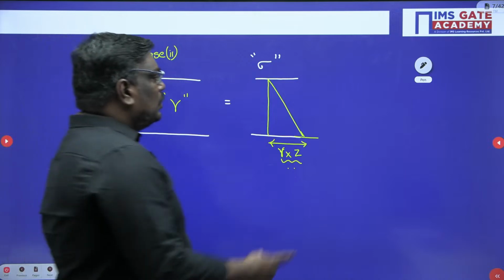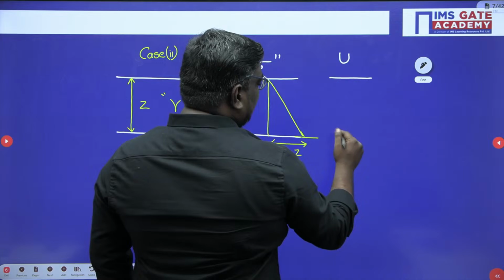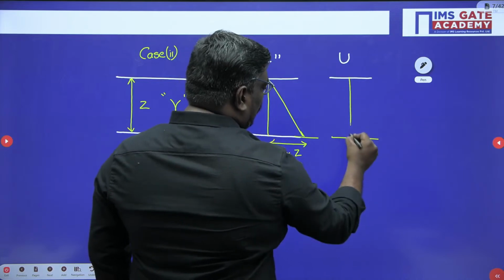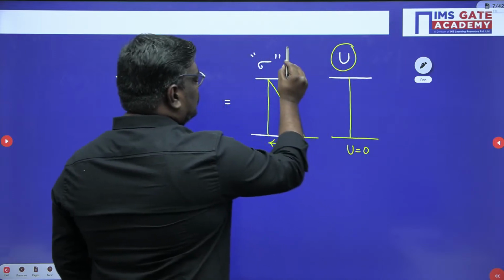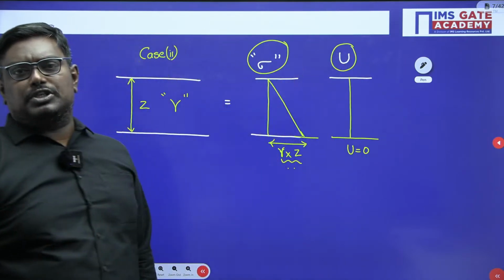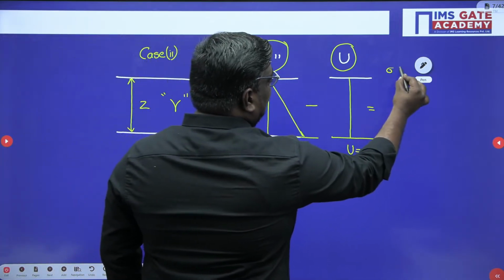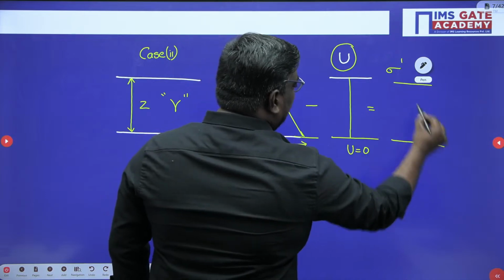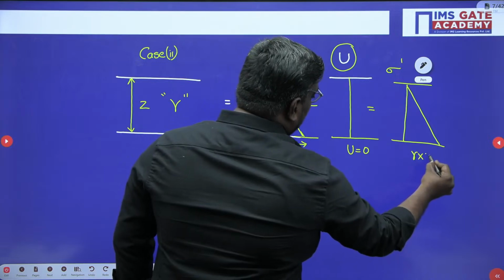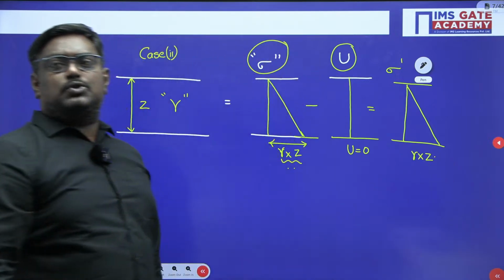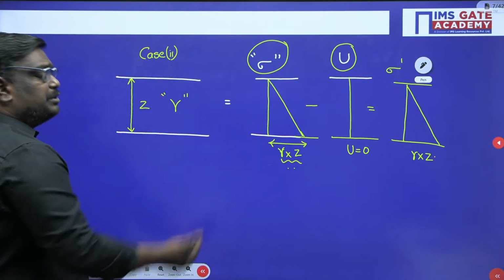No. So if I represent the pore water pressure here, the pore water pressure is 0. So you know the pore water pressure, you know the total stress. Total stress minus pore water pressure can be written as effective stress, and this can also be written as gamma into Z. So my dear students, very good Gagan, it will be in a triangular variation, or hydrostatic variation.